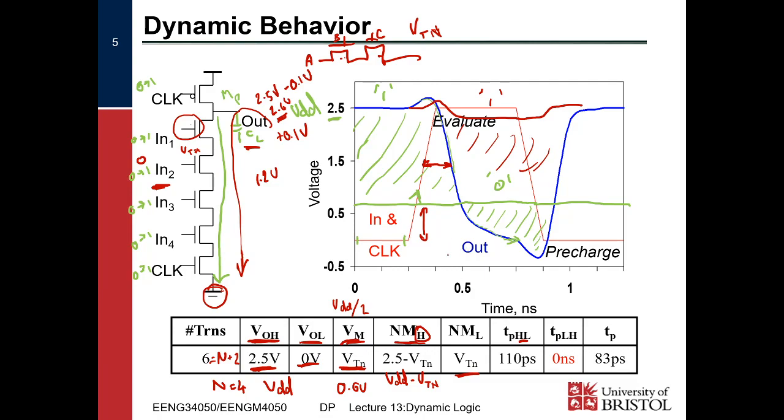So let's do a simulation in some piece of circuit simulation software. Maybe it's the IBM process this time. And we get 110 picoseconds out of it. Okay, so that tells us how long it takes to discharge our output through 4 transistors, right? So that's for a 4 input gate, we've got 110 picoseconds maybe.